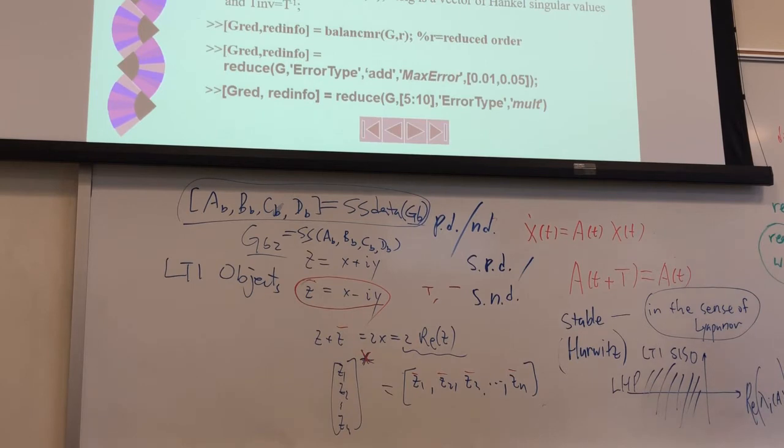So here is the question. I have ordered the Hankel norm in here, the Hankel singular values, sigma 1 and so on. So let's try to decide the bottom R. The first R I'm going to keep, and the bottom n minus R I'm going to delete.